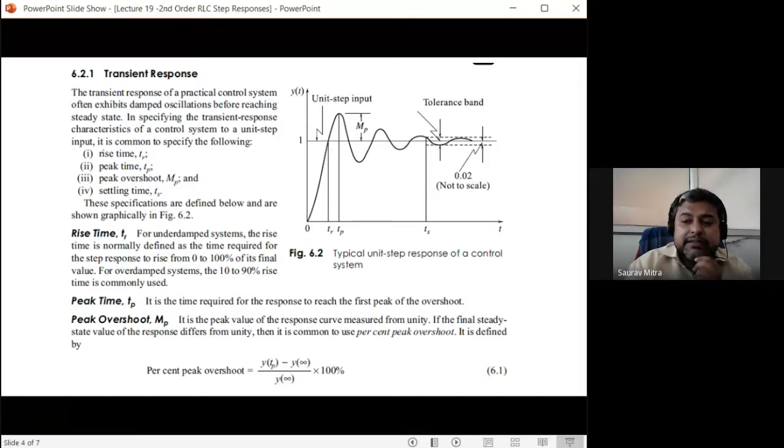Okay, there is another definition which is not shown here. It is called the delay time. What is the delay time? Delay time will be half of this height. Wherever the output touches the 50%, so in my notes I will show you, wherever the output touches 0.5 amplitude, that time you have to project below, and that is called the delay time, given by TD.